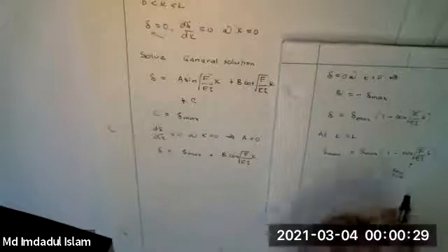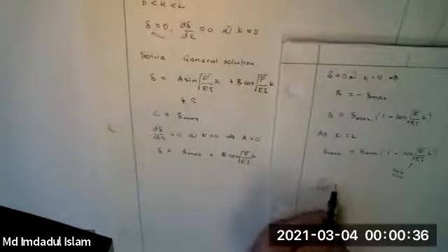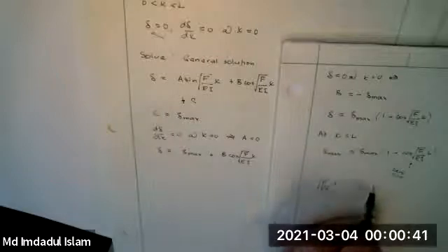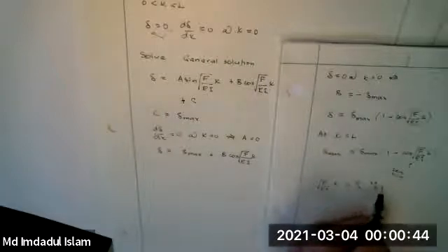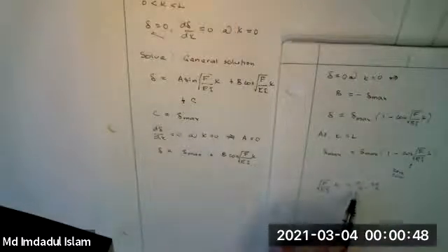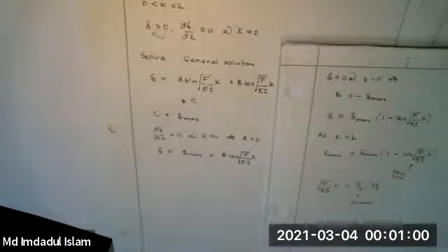Well, there are a range of values for that to be 0. The first one is when it's pi upon 2. Next one's 3 pi upon 2. Next one's 5 pi upon 2. We're going to get to pi upon 2 when F is increasing. F is going to get to this before this. So this is the first mode, the lowest value that gets you satisfaction of buckling.